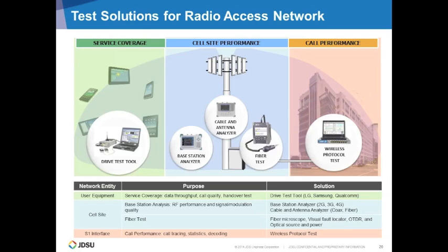In the next area, as far as cell site performance, I'm a huge fan of base station analyzers, especially when they provide me levels of visibility and details into the signal analysis. In fact, if I was troubleshooting a base station, that's probably one of the first tools I'd want to have at my disposal to isolate exactly what the problem is. They're very myopic, meaning that they can go to great levels of detail, but in terms of multitasking, they're not nearly as advantageous as a drive test receiver because they don't multitask quite as well.